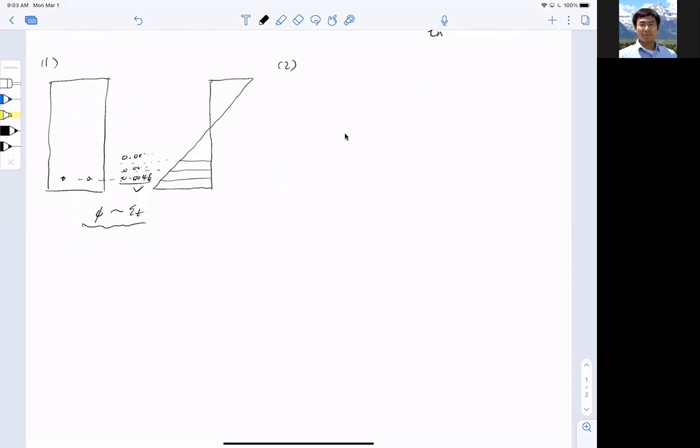It's on the doubly reinforced section. All right, I have observed some mistakes. One of the mistakes is that when you look at the doubly reinforced section, you ought to notice that regardless of the bar position, you always have to do the balance. That is, you want to use tension to balance compression or vice versa. But the problem is that you have to make sure that these are within 5% error at best. Worst case scenario, if you land at 10%, that's okay.